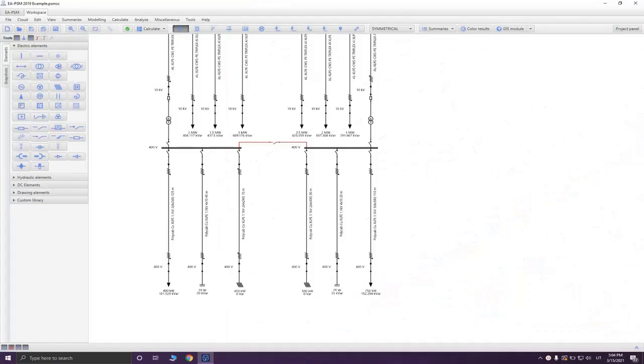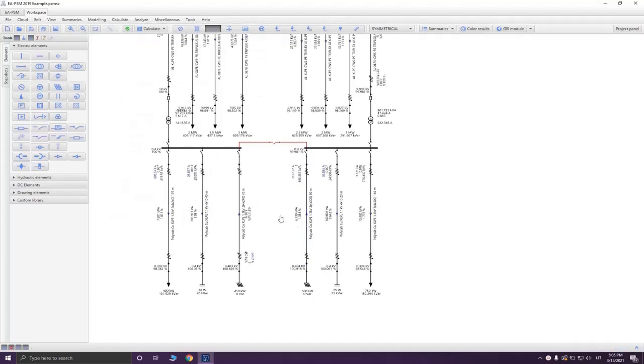When you're done choosing the parameters of your solar power plant, it is necessary to make calculations to check if the solar power plant is installed correctly. The first calculations that are needed are power flows. These calculations show how much current flows through your wire, the load losses, and what voltage drop percentages are at the bus bars.